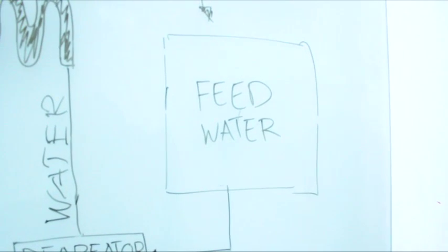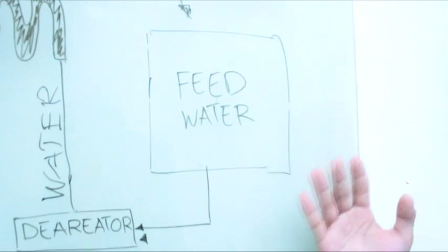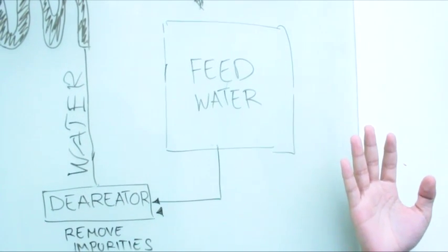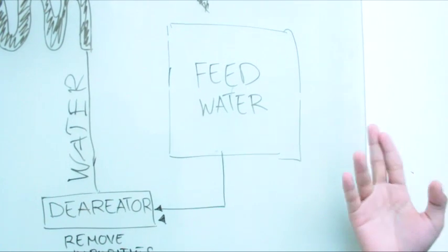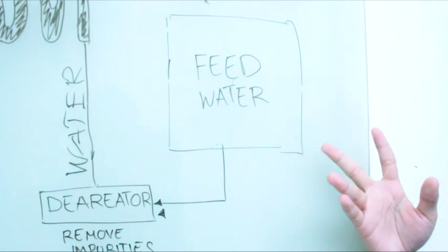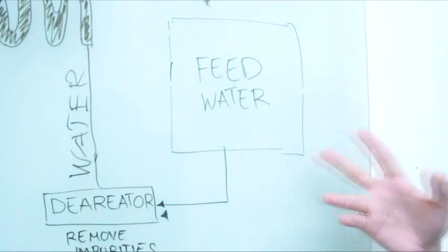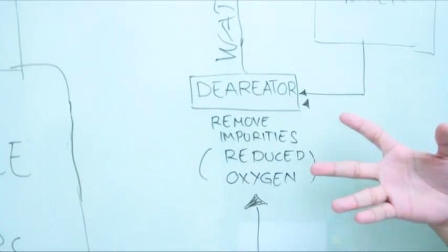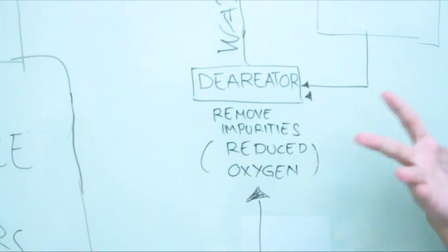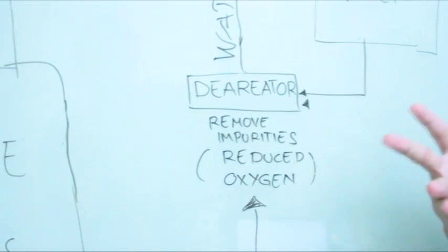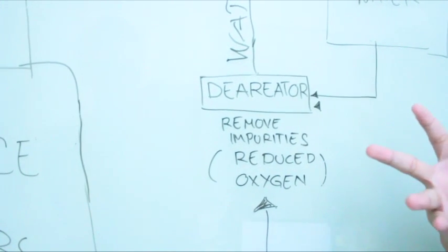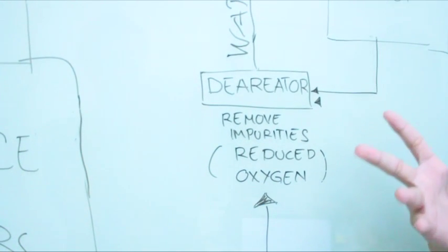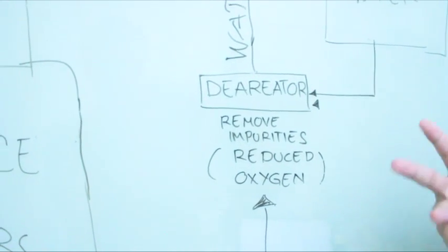Poor water treatment in the feed water may cause a buildup of solid deposits on the interior or water side of the tubes, and corrosion. To prevent it, it is recommended to ensure that there are no leaks in the feed water. In the next part, which is the deaerator, loss of water to it can cause a low water condition in the boiler, which will increase the temperature continuously, since no water is being heated, until the metals will be melted.